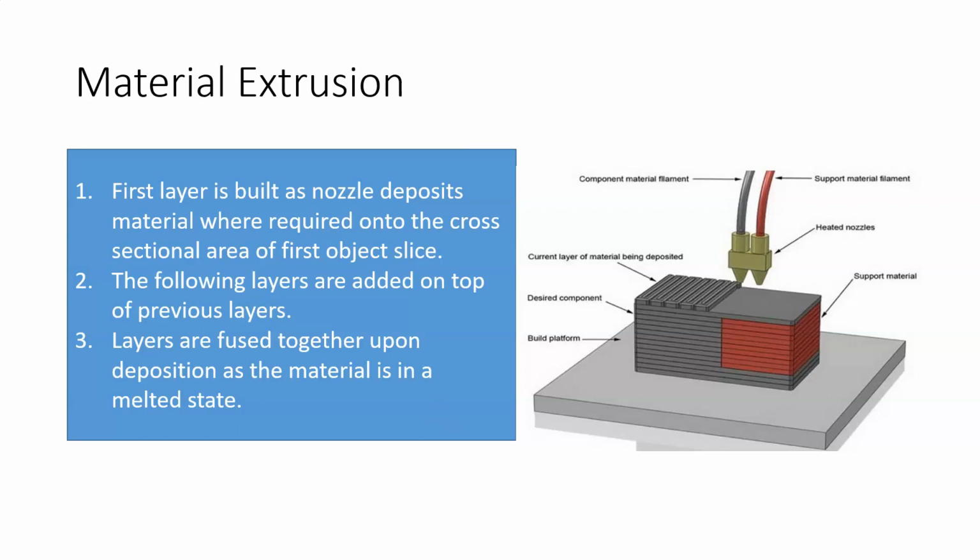Okay. So the material is going to extrude in a liquid state, but it's going to solidify rather quickly. And it's basically, it has to solidify, not necessarily 100%, but it has to solidify enough by the time the first layer is done so that the second layer can be deposited on top of it and, as I said, maintain its structural integrity, maintain its geometric profile and shape for the different layers. Okay. So that's the basic outline of the material extrusion process.